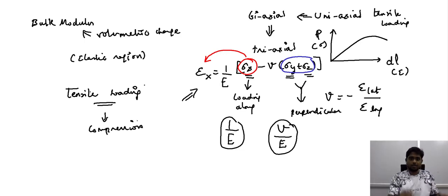So principally our discussion has largely been confined to tensile loading. However, since we have arrived at the numerical expressions for how the material would respond for a given triaxial tensile loading, from this expression we will be able to extend what the response will be for combinations of both tensile and compressive loading, and also the resulting response when we have just the compressive loading alone.